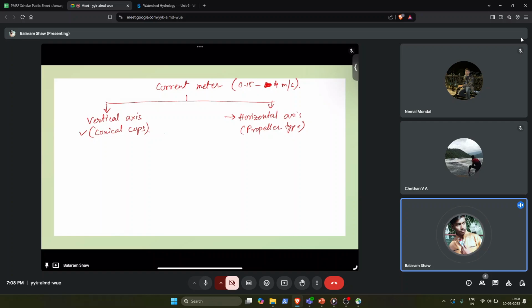So next, this one is using the current meter. Next, to calculate or estimate the velocity, we see the velocity profile over a section. So let's say if you cut the section of a river, then how the velocity profile looks like. At the bed, there will be no velocity, right? And as it moves up, it will have more velocity, and again it will reduce.